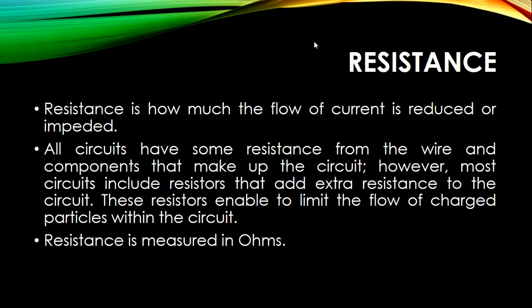These resistors enable us to limit the flow of charged particles within the circuit, specifically for an LED, because an LED has a tendency to draw more power, to draw more electricity, and this will cause the LED to burn out earlier than expected. So it is recommended that if you're going to use an LED, you have a resistor to prolong its life. Resistance is measured in ohms.